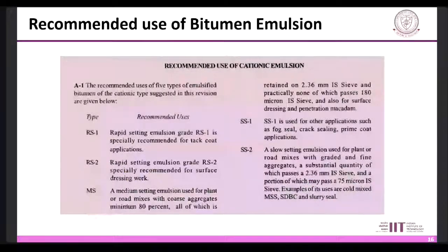The recommended use of bitumen emulsion: RS1 is generally used for the special recommendation of the tack coat, and RS2 is basically used for the surface dressing work.